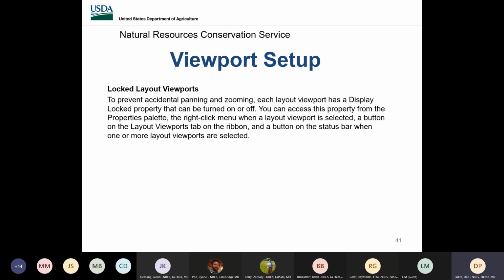I can't even hit the escape button. I don't know where I'm at. And then they finally got smart and made a paper space tab that you can hit and it'll get you back out of there. But in the past, they never had that. You almost had to escape out of the function and hit the undo button to get back out that way. But I'll go over that too.